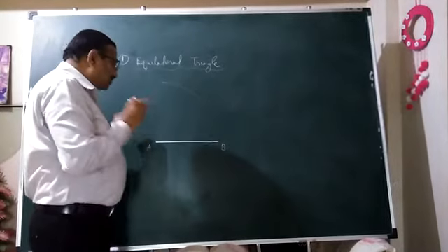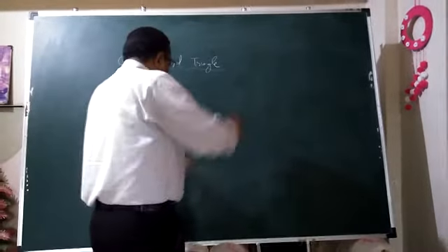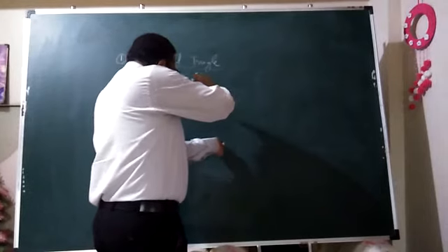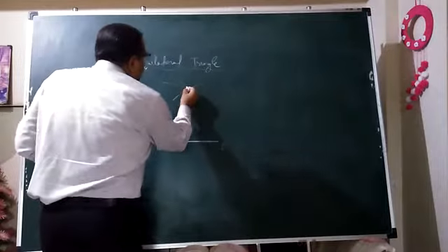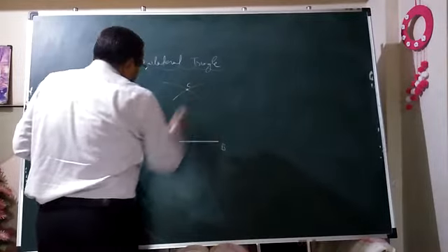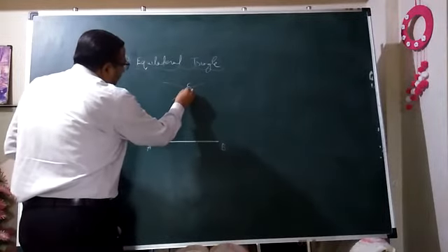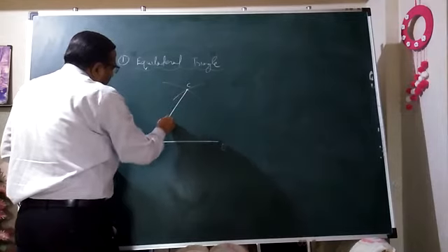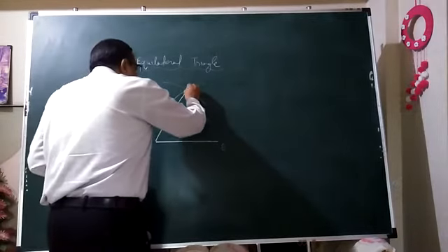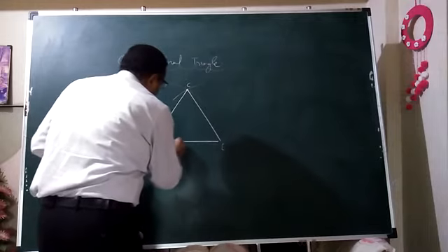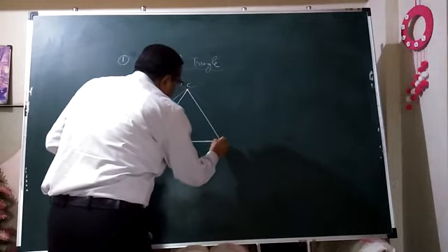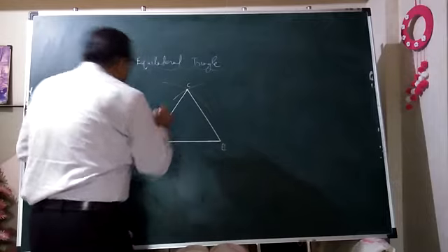Now interchange the position of the needle. Now instead of A, the same needle you have to place over B to get an arc intersecting the earlier drawn arc. So this point of intersection of both these arcs is nothing but C. When you connect it with A and B, naturally you are going to get a three equal sided figure, which is called an equilateral triangle.